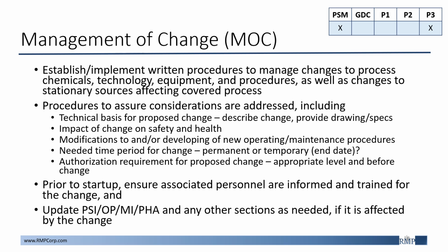Note that if the MOC is not completed, it will delay the PHA process. It is very important that all documentation has been updated to reflect all the MOCs prior to your PHA study, as any changes made after the PHA would invalidate the results of your PHA.